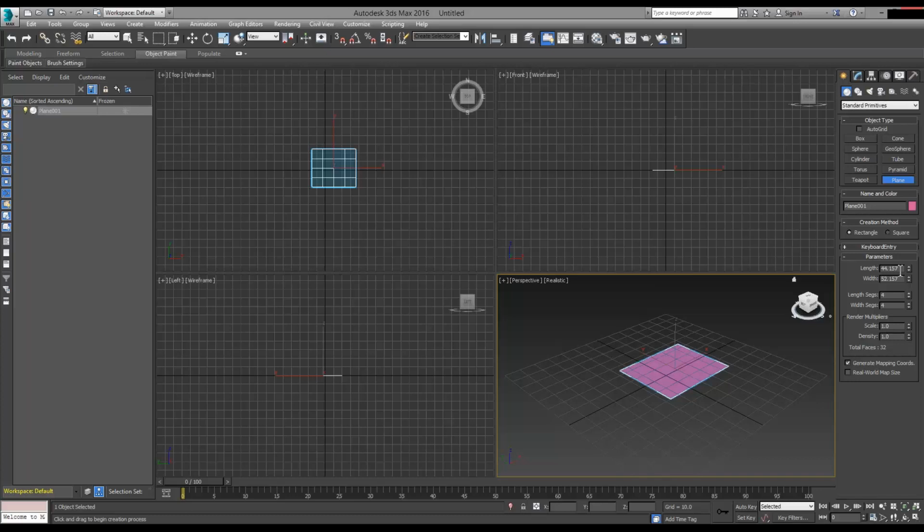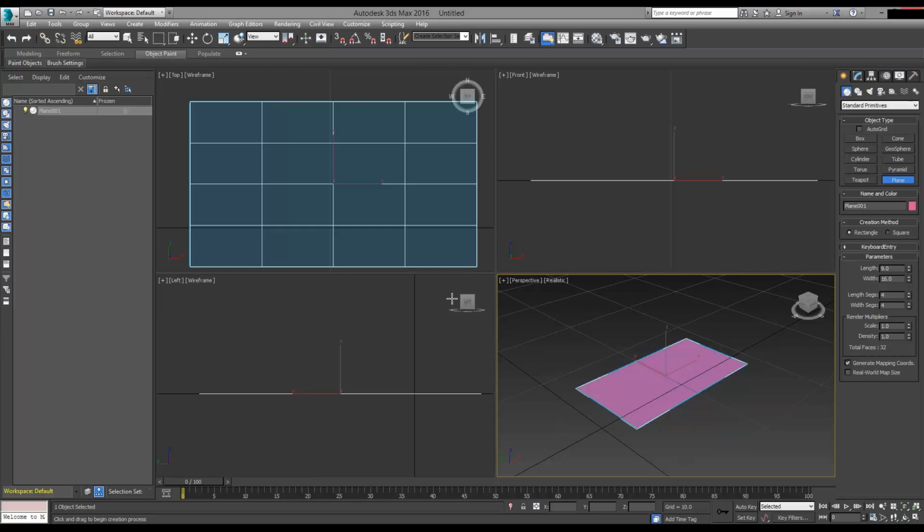And as I have a 16:9 screen, my horizontal generic units is 16, and the length in here should then be 9. So now you already see that it's a little smaller. A nice trick to get a nice view in here: I've selected the object currently, and if I click the button down here, zoom extents all, I see those viewports and my object in here.